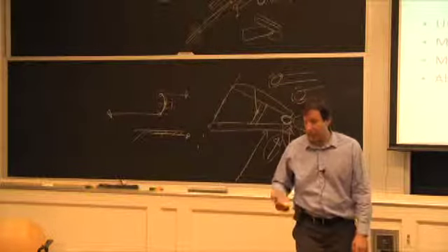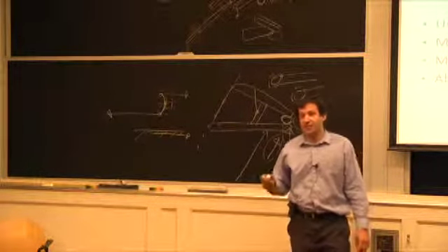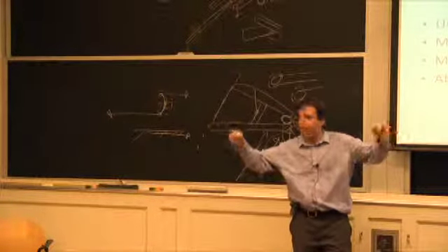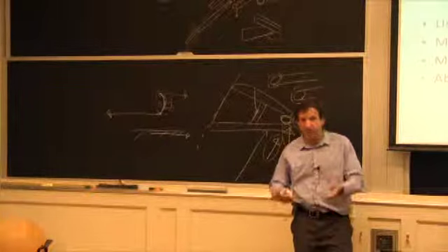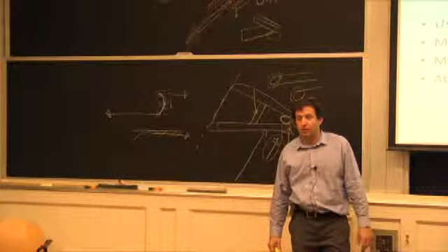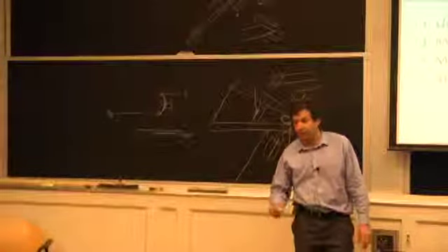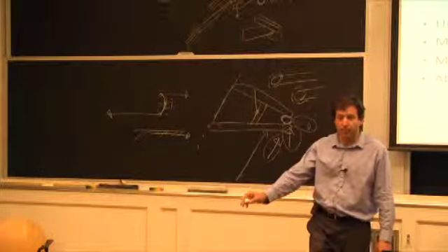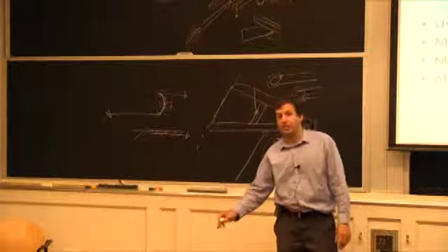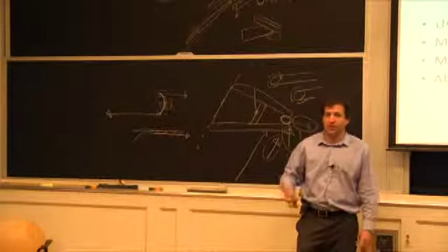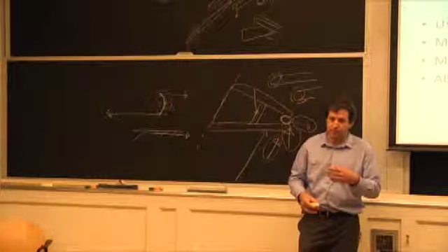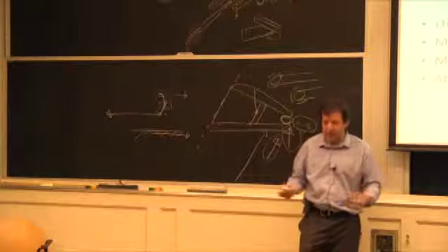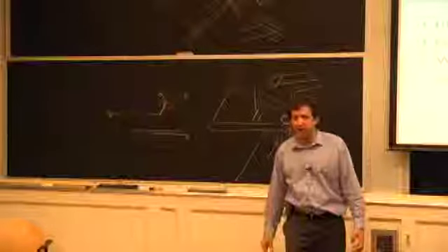Now, the problem there was, now it's done. So what exactly are we going to do about it? The whole structure is there. They have walls. They have a roof. And this guy came and drilled some holes. Well, the first thing I said, that everybody was very surprised by, was, don't plug weld them, because you're actually going to make the situation worse. Welding will add residual stresses to your situation to the point where, when you get the plasticity, you're going to be more likely to initiate cracking than if you do nothing.